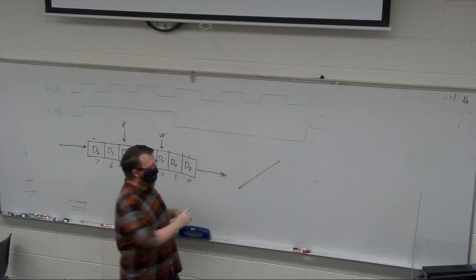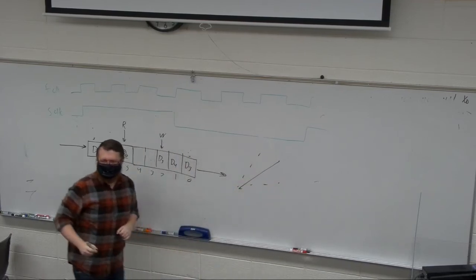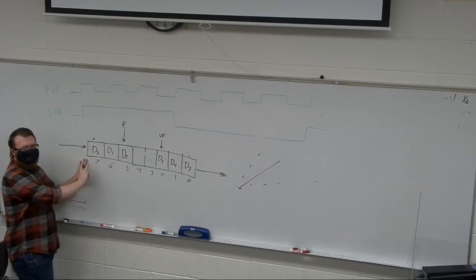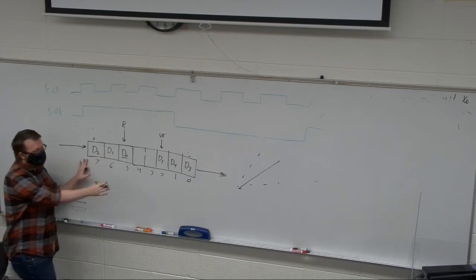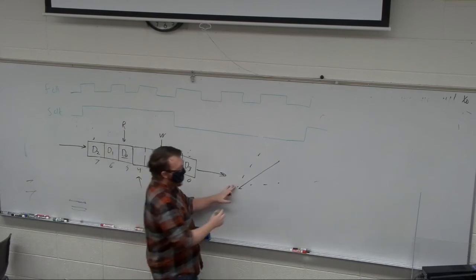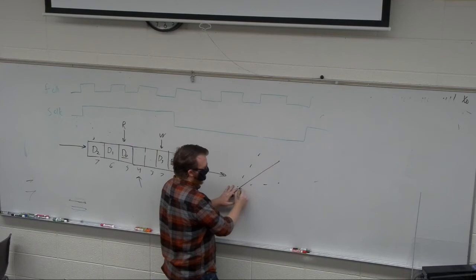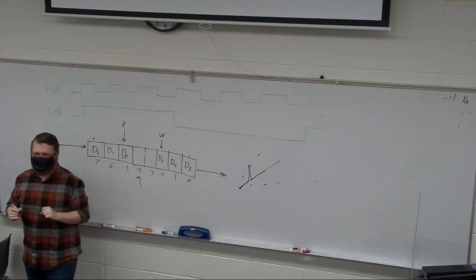And this is okay as long as it doesn't ramp up too quickly or too slowly, let's say. If I roll over, but in the middle of that, I take a random address because I'm rolling all ones to all zeros, I could end up pulling in the middle of this. And what it thinks it sees then is, so it has the cue to do this, but instead it does something like that because it's pulling from a future FIFO value.